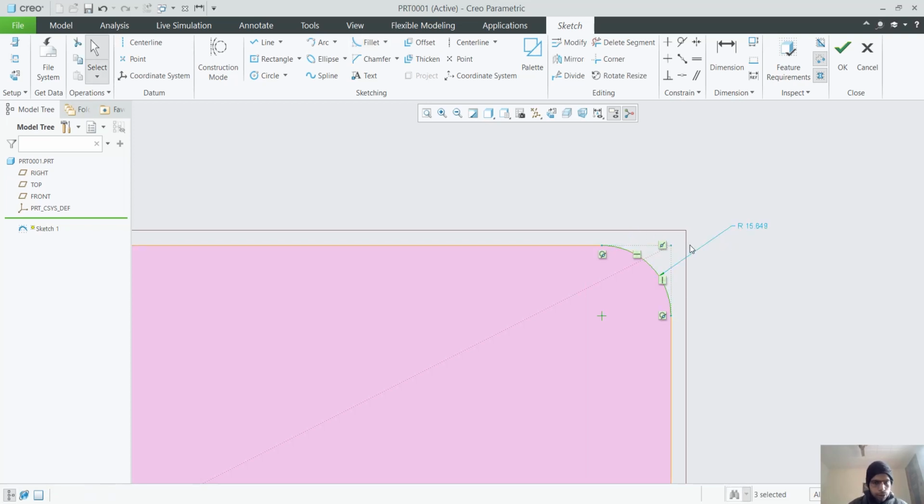Otherwise it doesn't. The point does not make it a fillet. You have to tell where you want to fillet. It automatically fillets by some distance. You can change it after you've done it, but it is not asking before, like in SolidWorks. But anyways, 10.